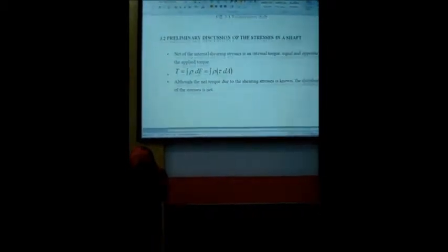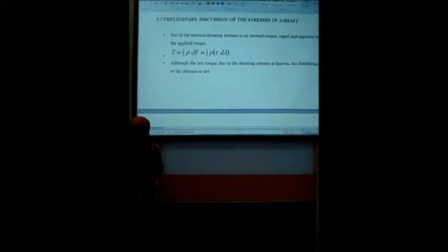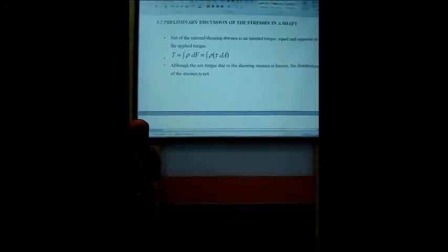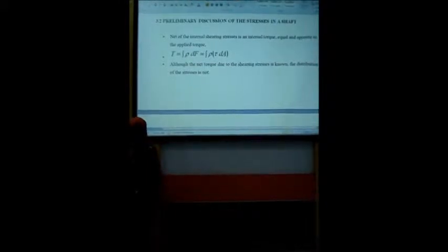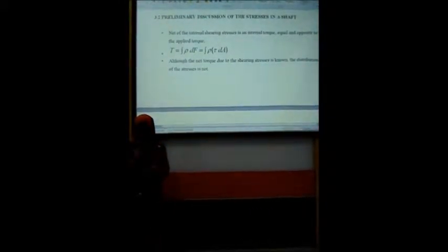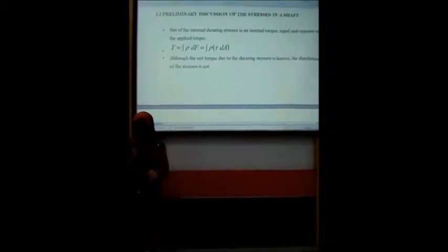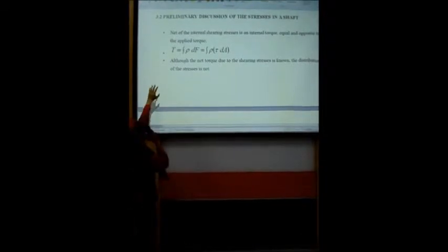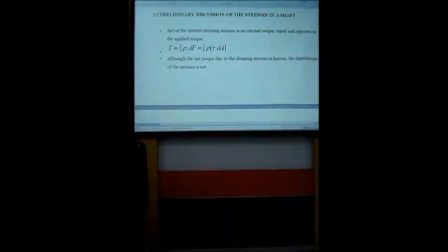Okay, next we move to 3.2, which is my topic. I would like to emphasize the preliminary discussion of the stresses in a shaft. The net of the internal shearing stresses is an internal torque equal and opposite to the applied torque, which is the formula shown above.